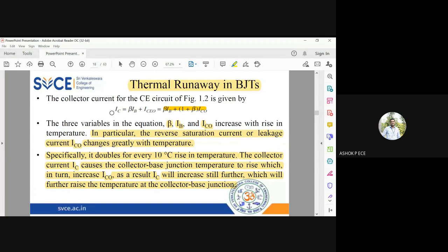The transistor is going towards which region? When the current is increasing in an abnormal way, is it saturation or cutoff? Saturation, sir. Saturation, yes. And the Q point is moving upwards or downwards? Upwards. Very good. See, that is the interpretation you have to understand. When a single parameter is changing, you should immediately say whether the transistor region is changing or the Q point is moving upwards or downwards.